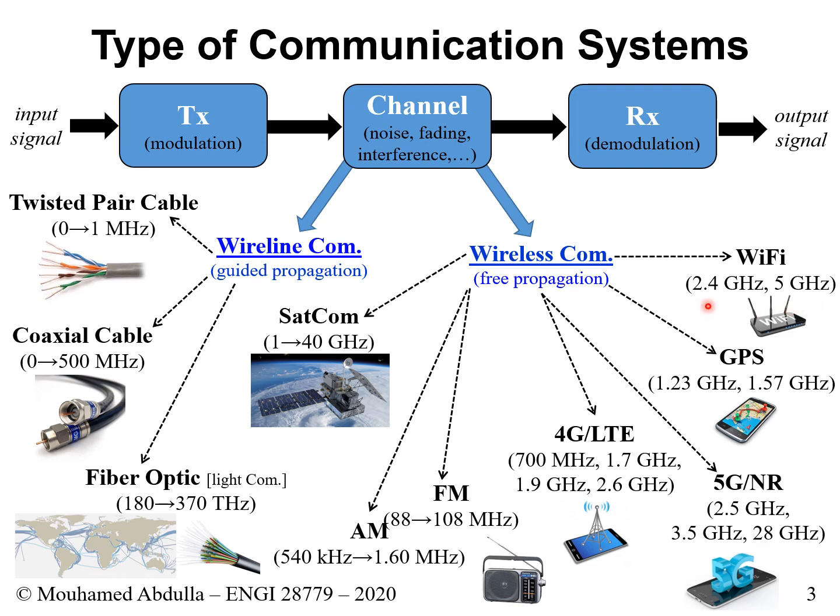Then the better option would be to go with 2.4 gigahertz. The 5 gigahertz will be very lossy. It will not give you a better quality. Although it's a high frequency, you expect faster connectivity, but because you're far and you have a lot of obstacles between the router and you, you would opt for 2.4 gigahertz. So this is an interesting fact to know.